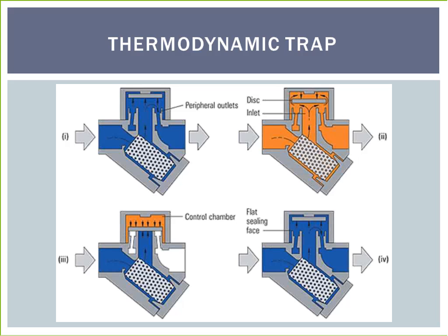Hot condensate flowing through the inlet passage into the chamber under the disc drops in pressure and releases flash steam moving at high velocity. This high velocity creates a low pressure area under the disc, drawing it towards its seat, shown in Figure 2. At the same time, the flash steam pressure builds up inside the chamber above the disc, forcing it down against the incoming condensate until it seats on the inner and outer rings.